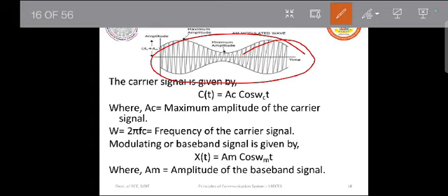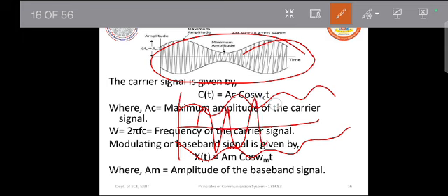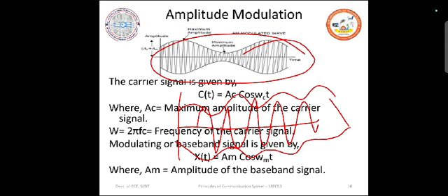So when you have a complex signal, the waveform may look something like this, and you can see the carrier wave filled in within this. So the envelope is no more a sine wave, even though it is looking like a sine, because it's a combination of many tones as such. So it will become a complex signal for us.